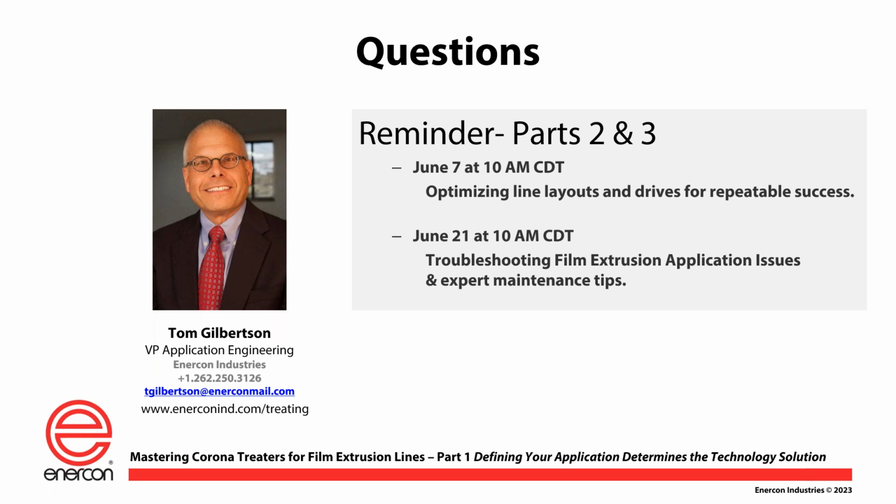The one thing I would say about that is there may be diminishing returns on that idea, depending on how this goes. It works really good. The idea is really good. If both the normal size power and then the future power can be done with a single electrode assembly on each side of the web, assuming we're talking a two-sided treater, great. But what happens if, once I get to the bigger power supply for the future, it requires more electrode assemblies, like 2 per side? You've really changed the economics here, haven't you?